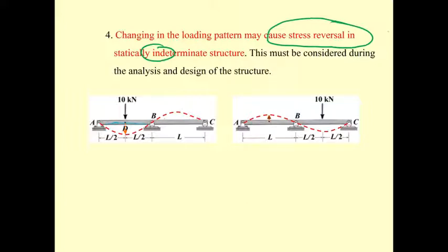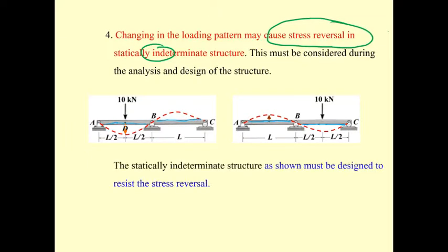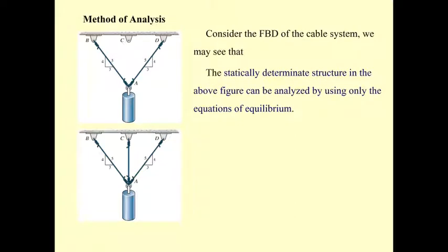This one, you put the reinforcement on the top, and this one you put reinforcement in the bottom, so they are opposite. So the analysis and design of structure must consider this stress reversal.